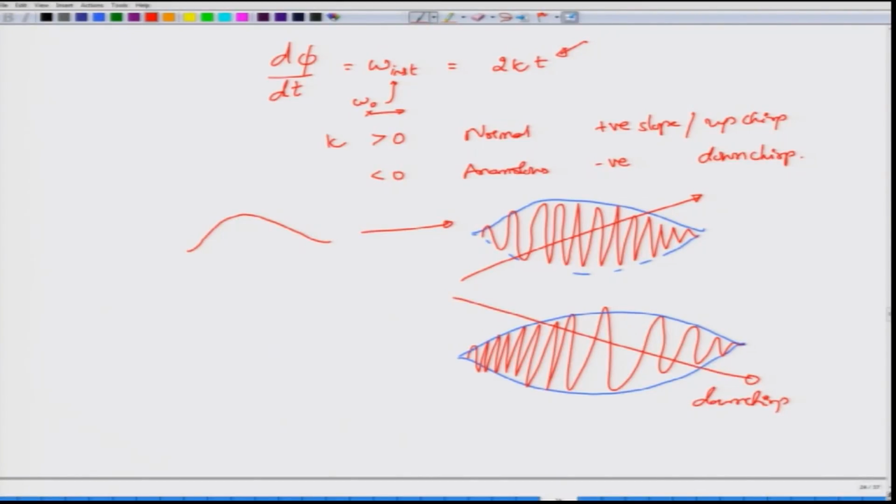So, the effect of dispersion on the pulse that is propagating, which is initially unchirped and Gaussian, is to retain the Gaussian character, and in the absence of losses have the same energy as the input, but this pulse at the output would have broadened out mostly, and it would also have acquired chirp. This effect is not desirable, and mitigating this effect occupies a lot of interest in fiber optic communication system design, something that we are going to see in the future modules.